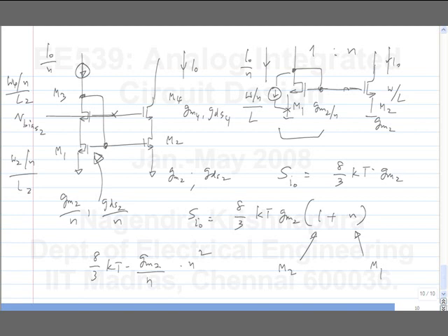You will in fact have to use the same current, and in some extreme cases even more current in the reference branch than in the main branch. There are practical cases where this is necessary. When the noise of the current source influences the noise of your circuit significantly, you don't want to do this. One example is voltage controlled oscillators.